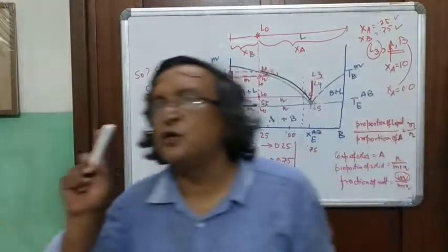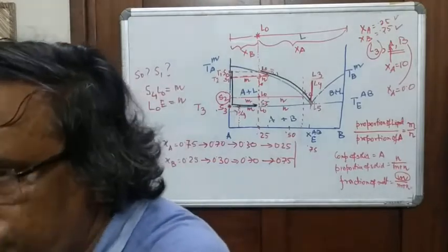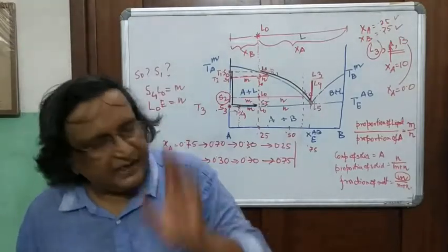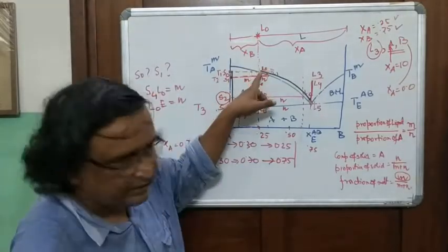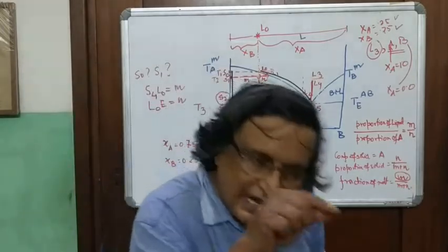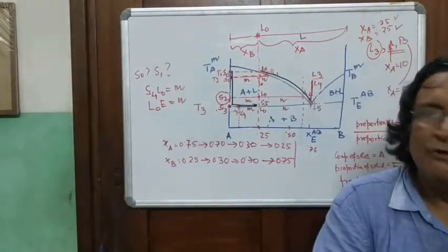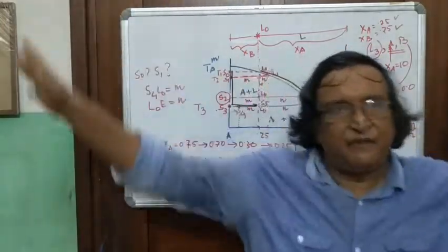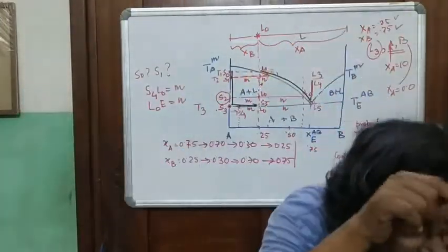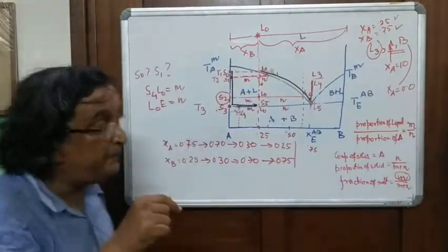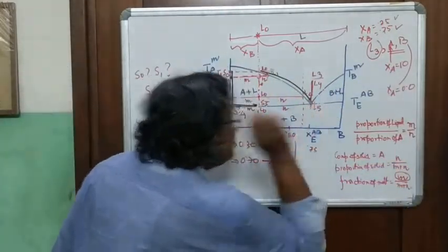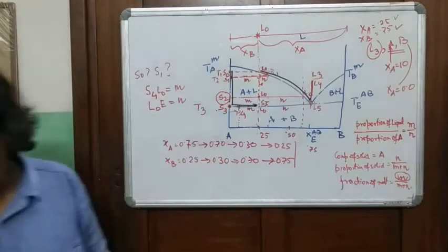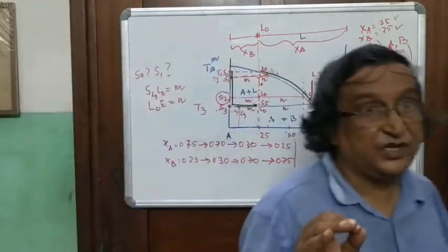That is very crucial. The composition of the last solid is the same as the initial melt. But the last solid was never in equilibrium with the initial melt. It never was. That last solid was in equilibrium with this eutectic composition. That is what it's all about.